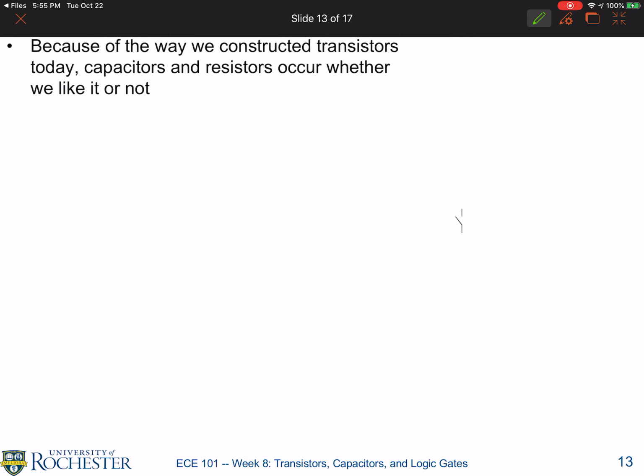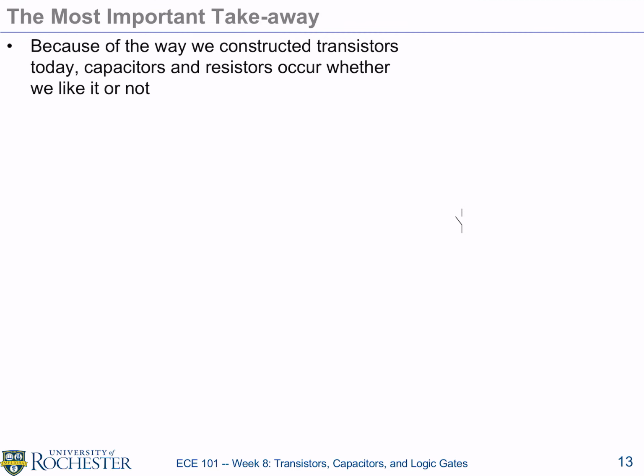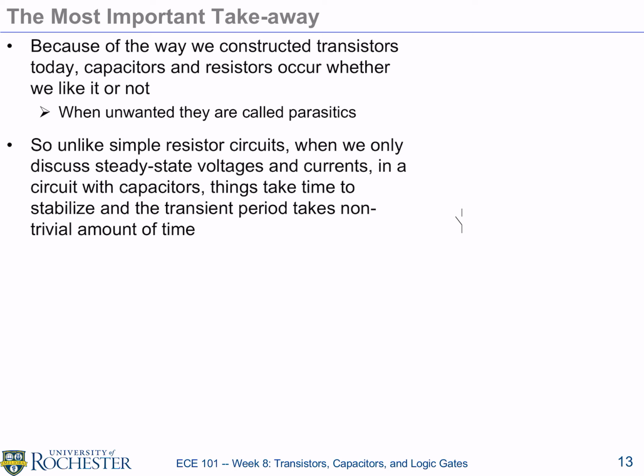If we want to solve this equation, we can, but what really matters is that the device that we're creating has resistance. We want the channel to have 0 resistance. Ain't gonna happen. We want the gate capacitor to be really small. That's not gonna happen. These are all unwanted and they're called parasitics.